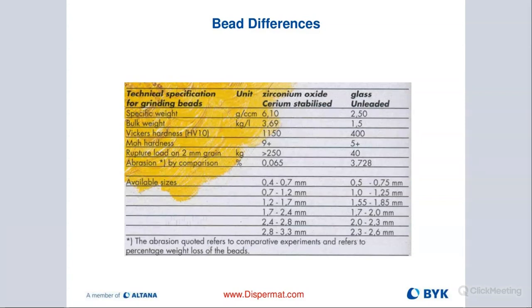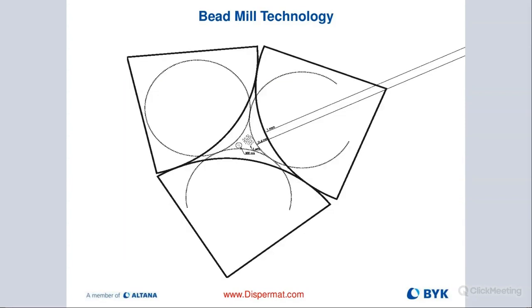Obviously, metal beads are not suitable for the application. Therefore, ceramic is ideal and has a really high hardness to get the job done. Stay away from glass. The good news is they're cheap, but the bad news is they shard and break up. You have shards in your slurry, and then you have to filter that out. It's not a good thing.